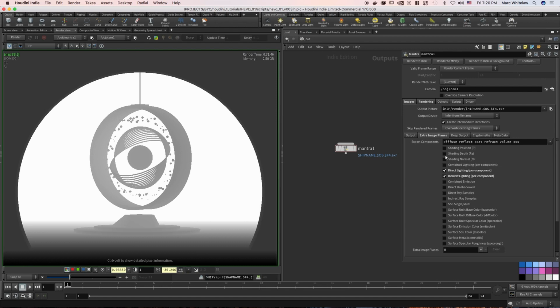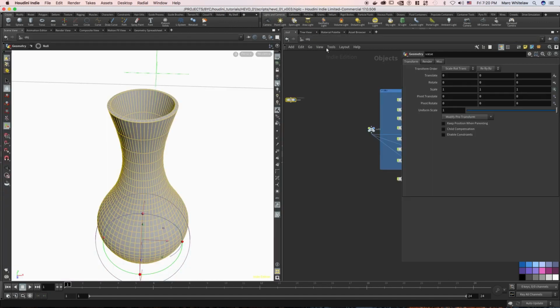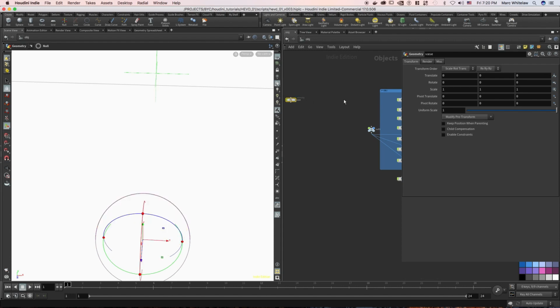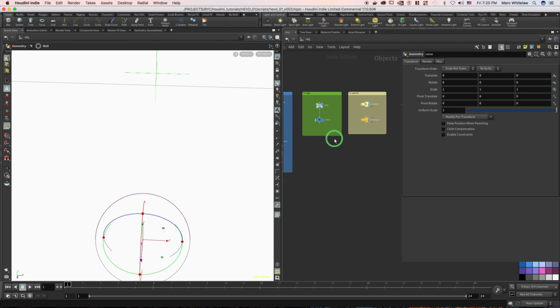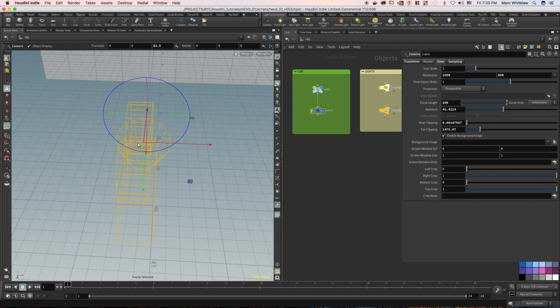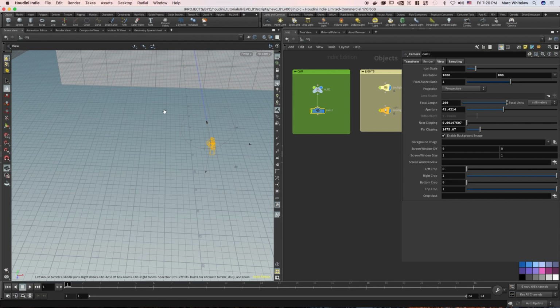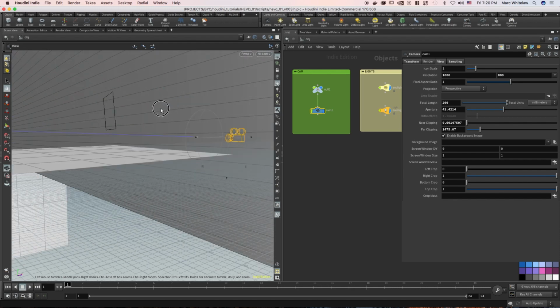And I got that by checking the shading option. And just remember, as a reminder, for the depth, you need to make sure that you set the right distance via the camera. You do that by coming into the view option here. With this transform control selected, you'll notice that we get this blue handle that shoots out of our camera.